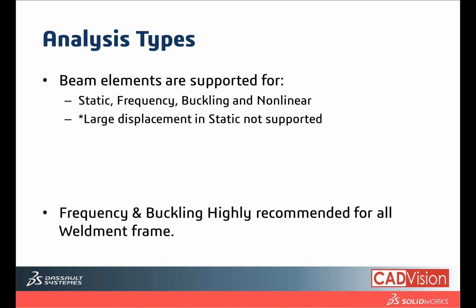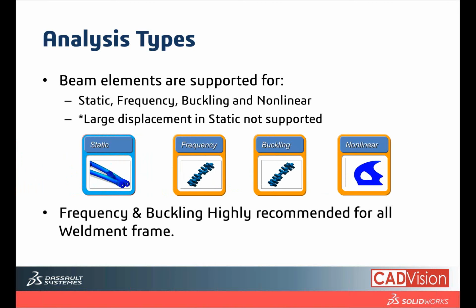Bear in mind that large displacement in statics is not supported for beam elements. So here are the 4 supported study types of Simulation where you can use beam elements: statics, frequency, buckling, and nonlinear. In some cases, such as frequency or buckling, it is highly recommended to use the weldment frame, right?